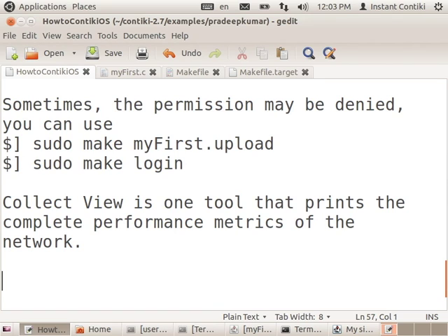Actually, my thesis is on IoT only, on power modeling of IoT systems. I never go for an application. Rather, I went for a system inside. So what I did is, I do not have any power calculation by default in Contiki. There is one thing called PowerTrace, and another thing called Energest. So the Energest and PowerTrace I modified as per my convenience, and then I calculated the power occupation of an IoT application. So this is what I have tried.